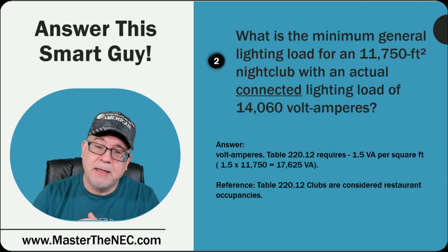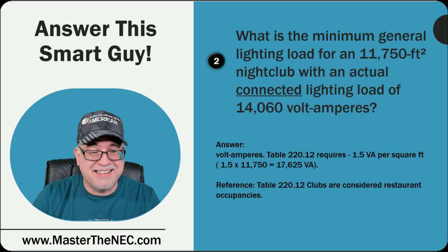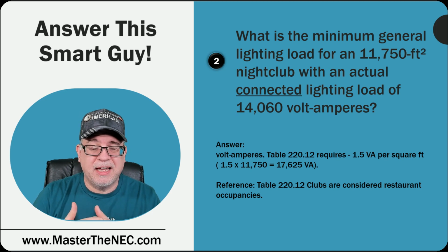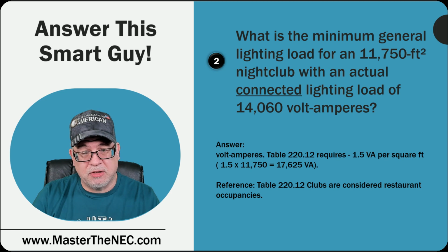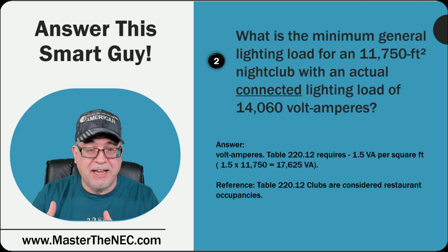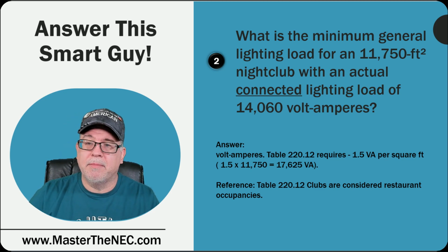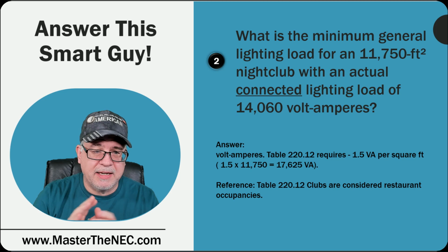Now, in this question, they were trying to drive you towards the connected load or the connected lighting load. And in this case, the actual 220.12 calculation bore out to be a higher value. Okay, good question. Might come on an exam. The one thing I'll remind you is don't overthink this question.